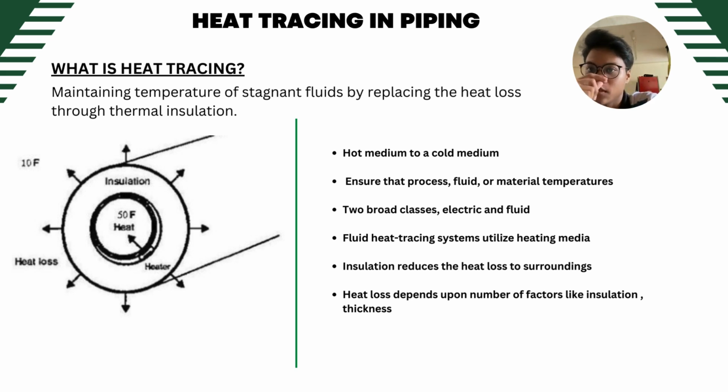I will continue with the part on theory and method. I will explain about heat tracing in pipe. Heat tracing means maintaining the temperature of stagnant fluid by replacing the heat loss through the thermal insulation. Also, heat tracing will never heat a flowing line, and if you lose your heating medium, you will lose the temperature downstream for the equipment.